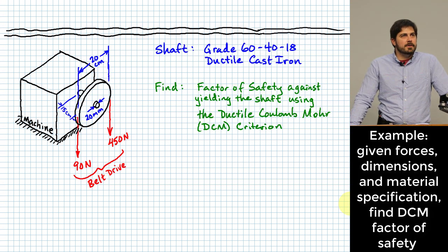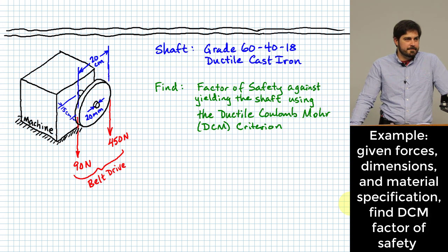All right, what we have here is a piece of machinery that is being driven by a belt. We might assume this is a flat belt. Flat belts don't transmit any torque unless you have some amount of pretension. To transmit torque, the two sides of the flat belt both carry tension, but they carry different amounts of tension as it drives the piece of machinery. That's what actually introduces torque into the machinery.